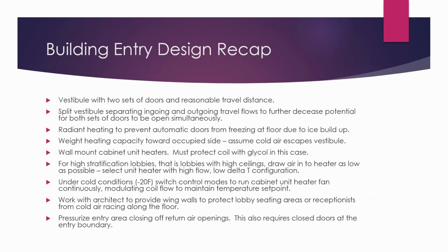Okay, so building entry design recap. Vestibules with 2 sets of doors and reasonable travel distance is the foundation. Split vestibule separating incoming and outgoing travel flows to further decrease potential of both sets of doors to be open simultaneously. And again, this has been done in a hospital, but other than that, probably is not necessary.